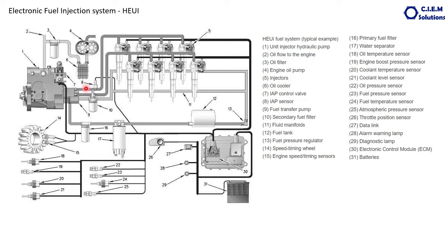The pump gets its drive from the crankshaft. There is also this small device called the injection actuation pressure valve. The purpose of the injection actuation pressure valve is to vary the volume and pressure of this actuation oil as demanded by the system according to the load variations in the engine.